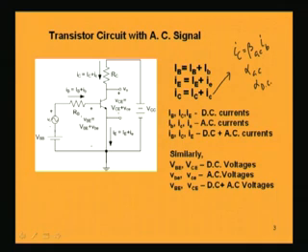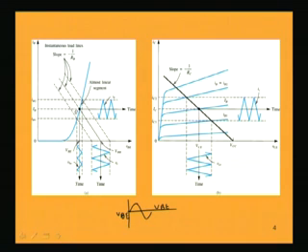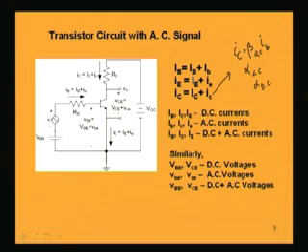So, for a constant RB, if we want to draw the load line, we take this maximum point of the base to emitter voltage, and then the point which will be maximum on IB, which happens when you make VBE 0.